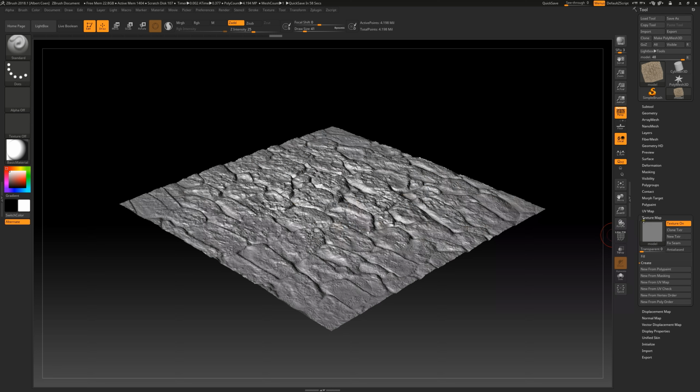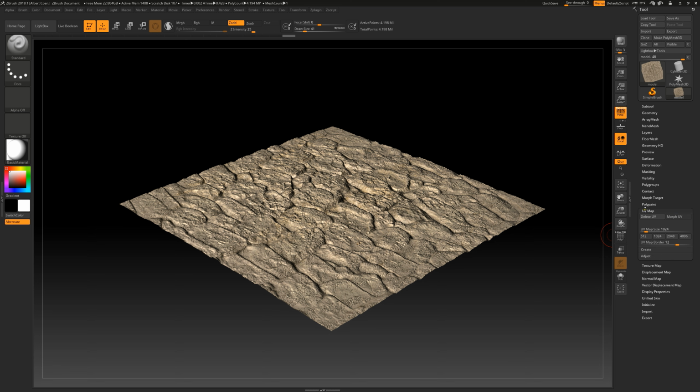Since our object has been poly-painted in ZBrush, we can easily navigate to the Texture section and then activate the New from Poly-Paint button. To set the resolution of our texture, we go to the UV submenu, where we can choose the preferred resolution, or adjust it using the slider. Furthermore, it is highly recommended to slightly expand the UV edges by 12 pixels along the seams and borders to effectively conceal the color information. Now we activate New from Polypaint, successfully creating our new diffuse map.